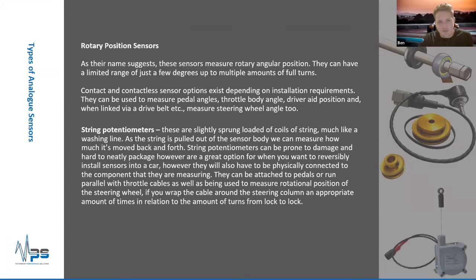Another way of quite quickly, easily, relatively cheaply, and this is probably my favorite for unintrusively, so no permanent modifications, can all be removed, is to use a string potentiometer. So particularly favorable if you're working with a road car, predominantly road car, just to do a bit of track days, etc. You want to install some sensors, but you don't want to be drilling holes in your nice dashboard and affecting the resale value.